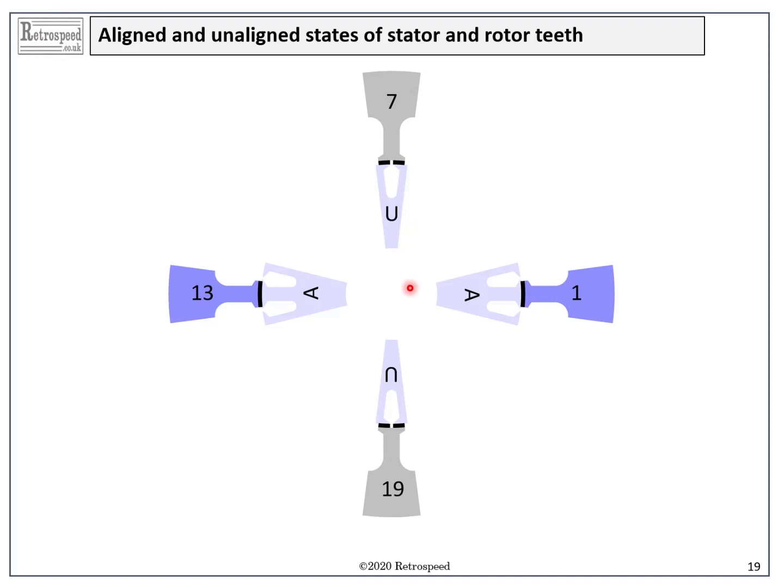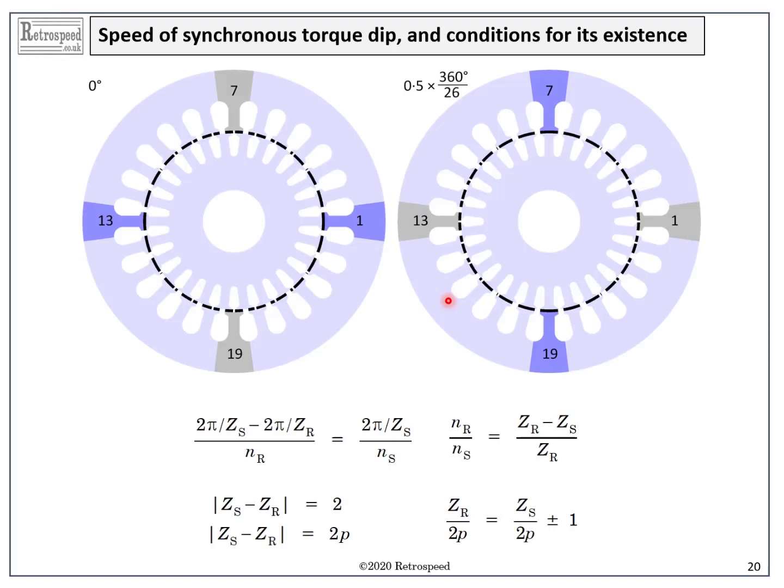Any stator MMF aligned with the x-axis will tend to align the rotor, even lock the rotor, in the aligned position. This is exactly the mode of operation of a vernier reluctance motor or slow-speed synchronous AC motor, and it is similar to the operation of stepper motors and switched reluctance motors.